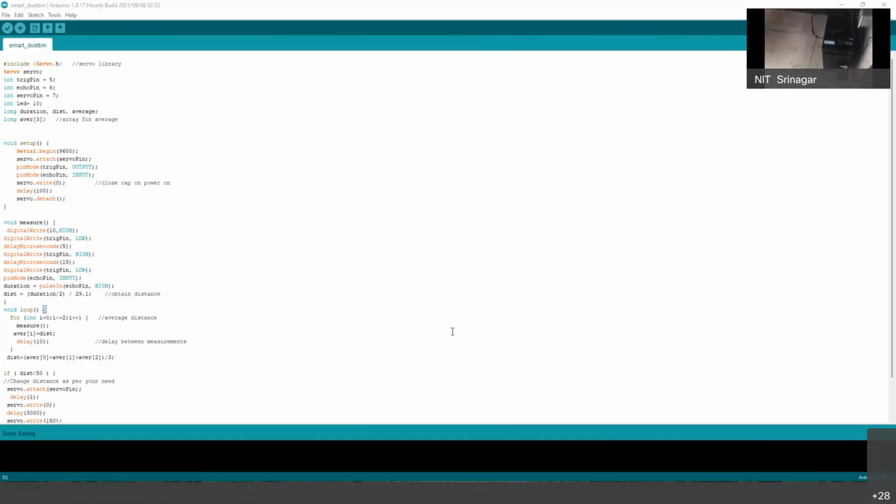Then moving on, what is the gateway which we are using over here? This is the gateway MIB 510, and we have to use a COM port because it is directly communicating with the system. So we need to mention the serial port. This is important because at the application layer you need to mention the port number as well, so that it can directly communicate to that particular application level, at which particular application service you are using. So what will be the baud rate for this? Then finally, advanced server settings, or you can go for this.